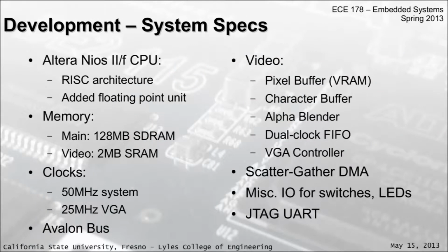So real quick overview, hardware-wise, I designed a system using the Nios 2/f CPU. That's Altera's performance-oriented version of the Nios 2. It has an embedded cache, faster instruction fetch.